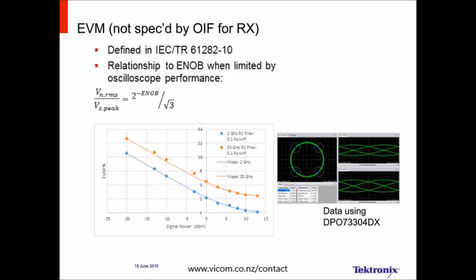And EVM is not one of those because EVM really comes from all of those other measurements. But if you'd like to measure EVM directly, then this is a kind of a nice way to do it, is just to put in a heterodyne signal and then demodulate it as if it was a QPSK signal. Because there's no modulator there, there's not going to be any modulation error, and so the error you measure is from the analyzer itself.